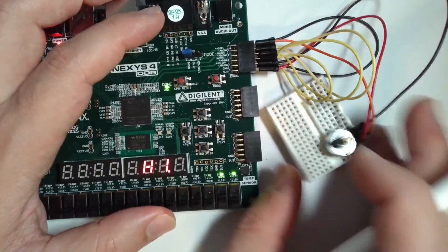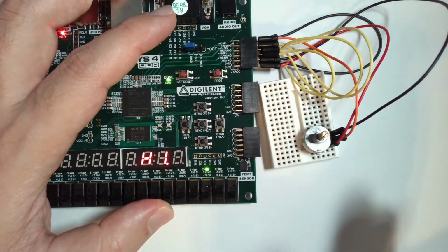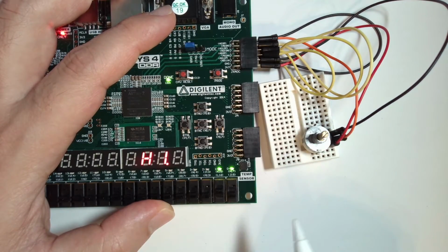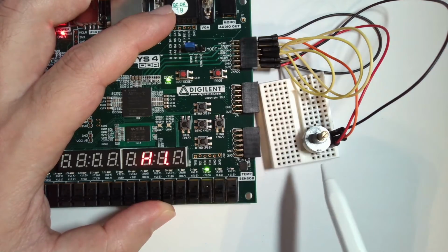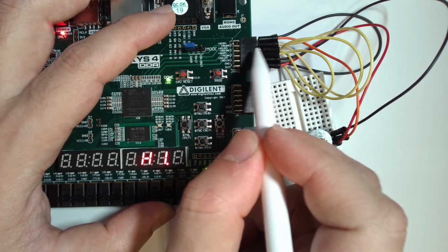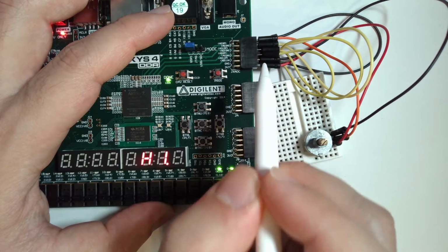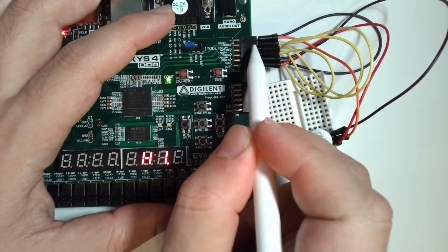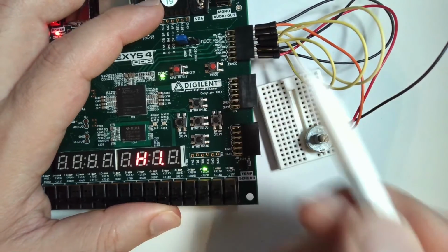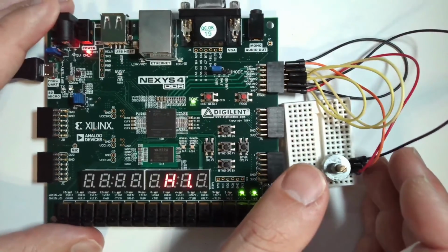So for the other ADC channels, in our test, I don't want to put so many potentiometers in here, but you could use, for each one of the ADC channels like 1, 2, 3, and 4, four different potentiometers if you choose to. But for now, I'm just showing you one. Because these ADCs are just left open, in order for me not to see anything coming on their numbers, I took the positive edge and connected it to the negative edge. Each one of these yellow wires is connecting the upper ADC pin, positive to the negative, positive to the negative, positive to the negative. Effectively, what I'm doing in the differential input is making them 0, and hopefully I get to see on the ADC that it's a 0.